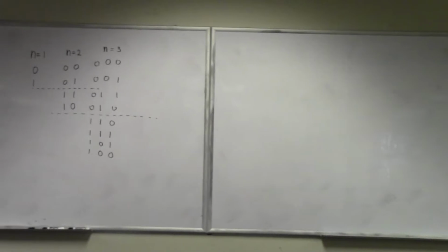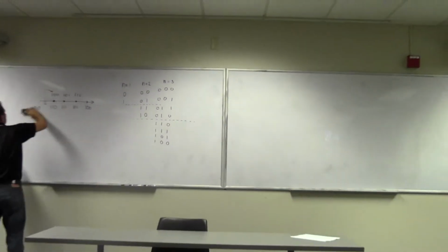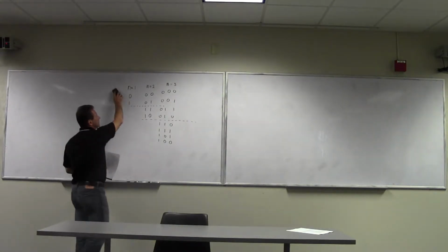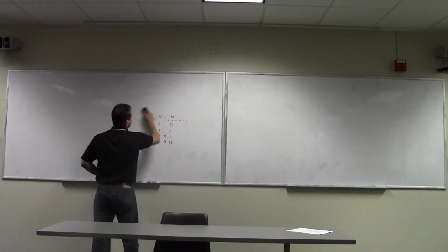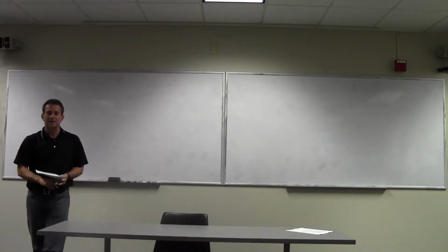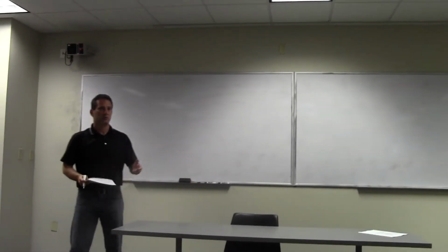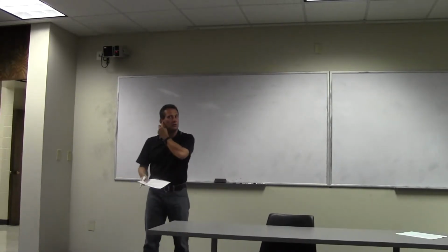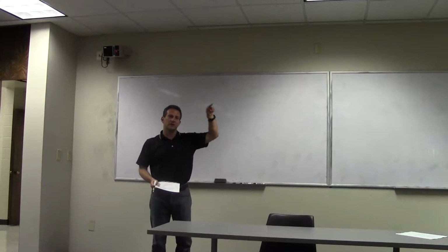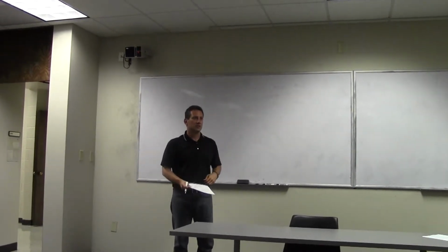What I'm going to do today is show you how you do that using two-dimensional signaling. Namely, I'm going to talk about PSK. PSK is the simpler of the two-dimensional signaling schemes. You're using the two vectors that you have, but in a restricted fashion. Every symbol has to be on a circle.